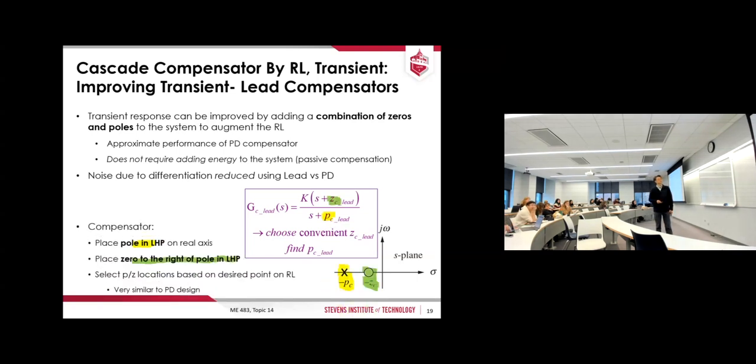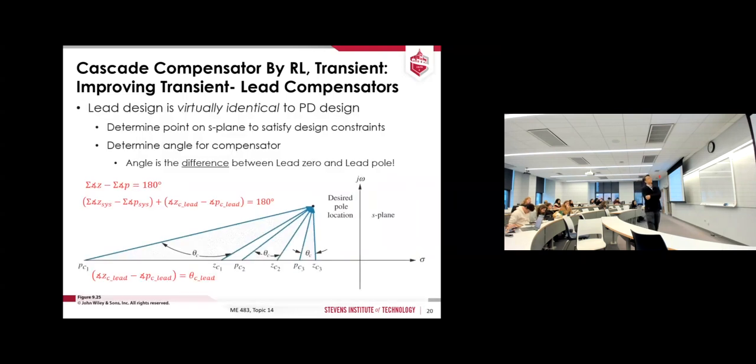Okay? It is very similar to the PD design. So the phase lead design is virtually identical to the PD design, but since we have this lead pole, not only the lead zero, that is the only difference.